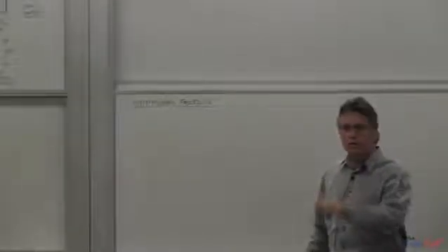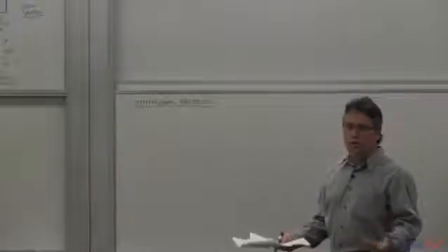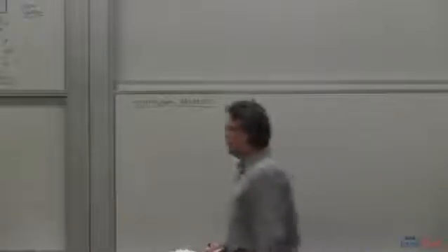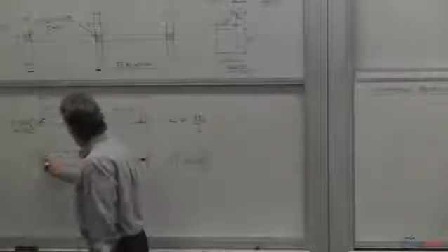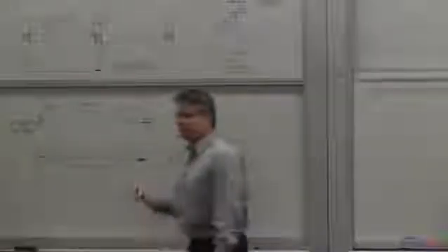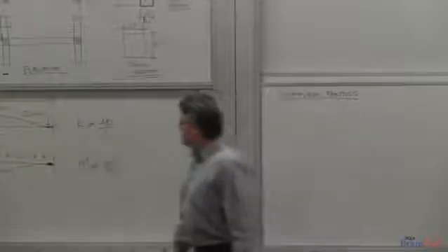Well, I got tired of doing what I'm going to say to you, and I actually wrote my own program using moment area. But hopefully you've learned moment area before. Just go back to your structural analysis book. It's not a lot of fun, but it's useful. But the easier way to do this is go to Visual Analysis or RISA or SAP. Build the beam. Build a 62-foot long beam. Make 1 foot of it infinitely rigid. Give it some reasonable moment of inertia in between there.